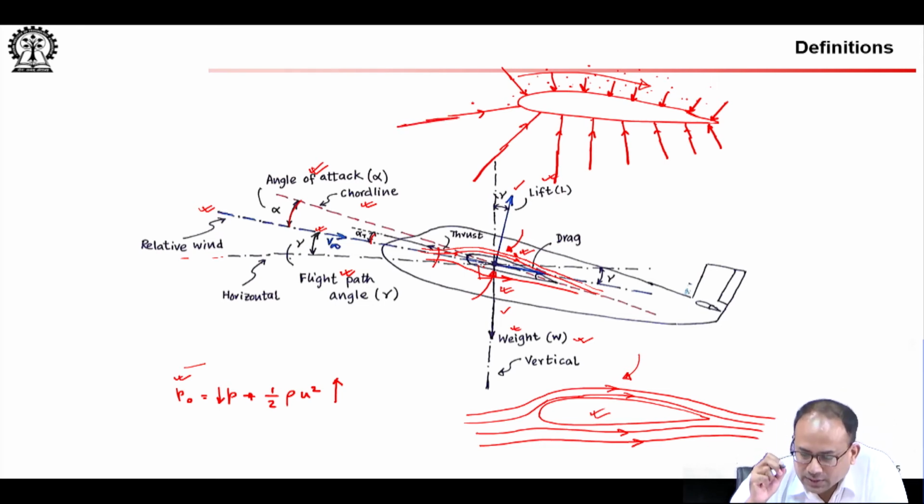So, what that will do is, if you integrate the effect of these forces, what you will find is there is a lifting behavior that will come in. So, the lower portion of the wing has higher force, the upper portion of the wing has lesser force. The resultant of this normal distribution will act through a point which you can think of as the center of pressure.